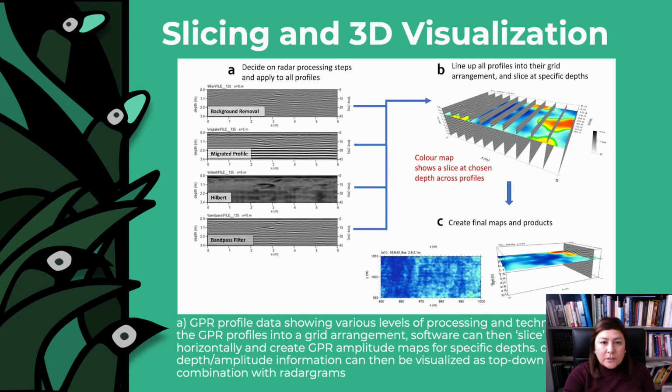Interpreting amplitude maps has several advantages. The reflection patterns are presented in a relatively intuitive way. One can inspect surface reflection patterns at any depth, and one can usually scroll up and down the slice depths to get a picture of subsurface features at various depths. It should also be kept in mind that slices are an interpretation, meaning they are based on a smoothed and transformed dataset. Using both GPR radargrams and these depth maps to understand any anomaly or feature is vital to the interpretation process. Many GPR visualization software programs can combine these two forms of data to create impressive 3D visualizations of the subsurface. These tools can be used to create impactful and intuitive representations of subsurface features, including graves, and the soil layers in which they are embedded.